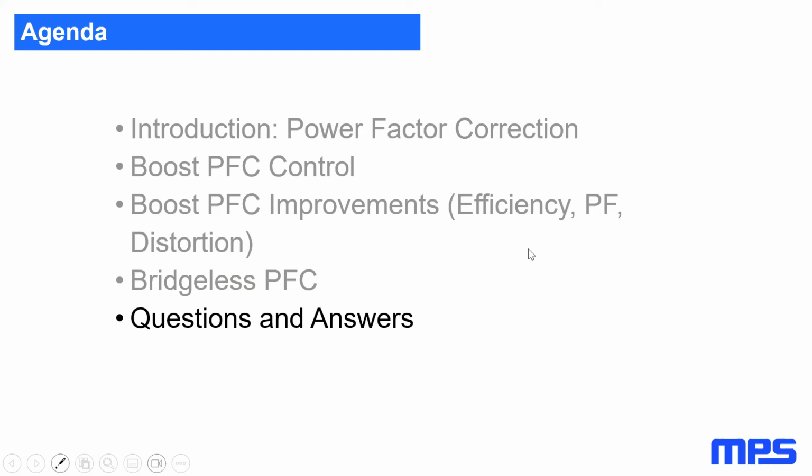Yes, there are. For example, we have this HR12XX family of parts at MPS, which we call a combo controller. So it has both the PFC control plus the DC to DC conversion stage in one controller. So this is PFC plus LLC or PFC plus flyback. And so yes, this exists.